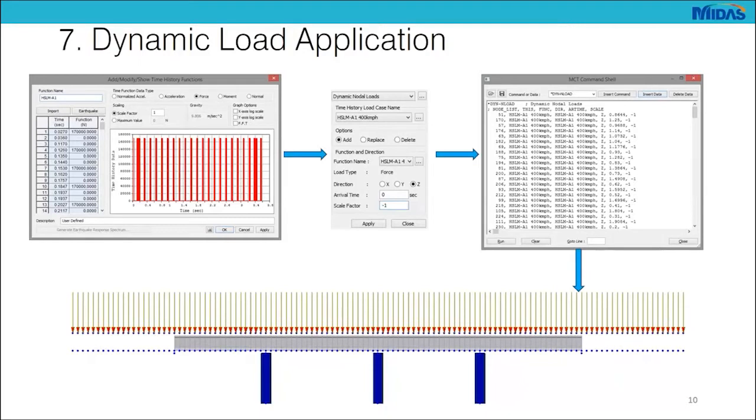Now once we've applied the dynamic load to one node, we can get the code-based input for that is internally used in MIDAS Civil, and we can see the pattern and how the values should be arranged so that we generate the load itself. And then in a simple Excel spreadsheet, we can easily create this format and then simply run it, and it will be applied just as you see in the screenshot below along all nodes of the deck or of the rail, depending on what we choose to consider.